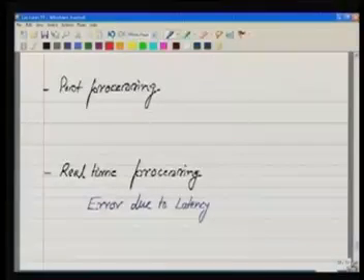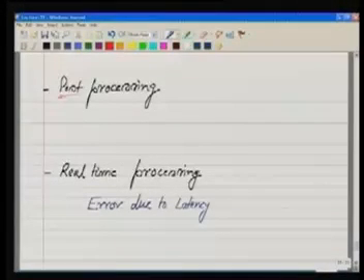So because of the change in the satellite position, because of the change in the atmosphere, because of the perturbations in the satellite, the corrections will change. So we need to transmit the corrections continuously to the rover in order to locate the rover position accurately. Now what we can do, we can go for 2 kinds of processing of the data.